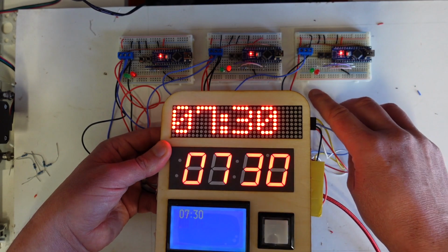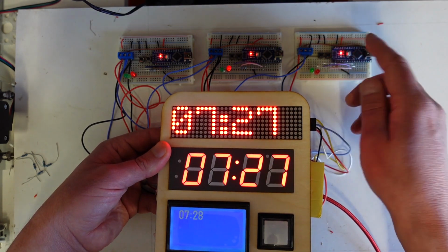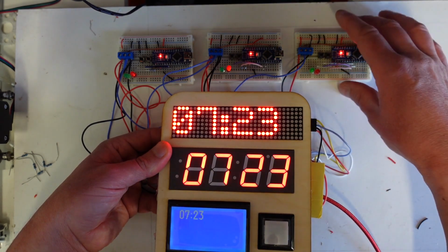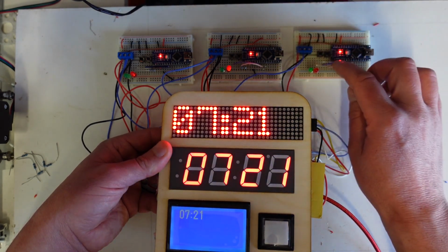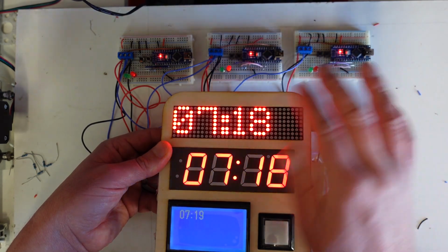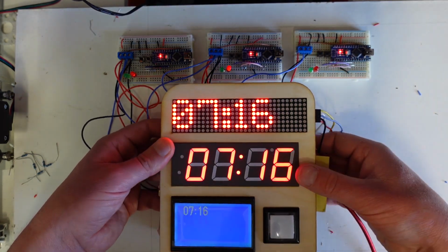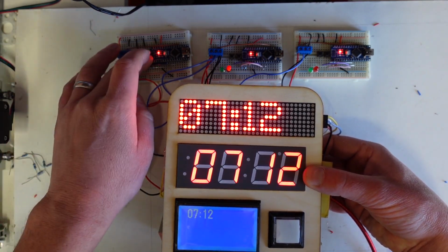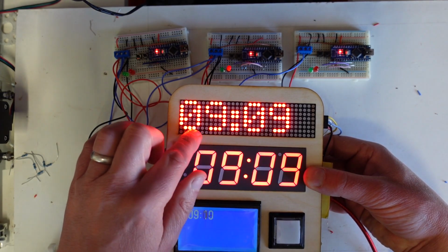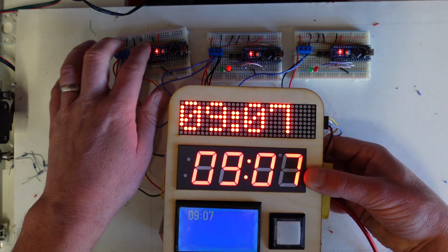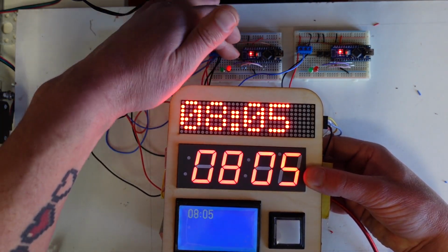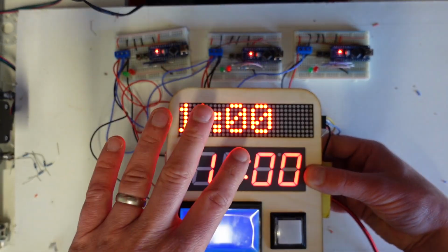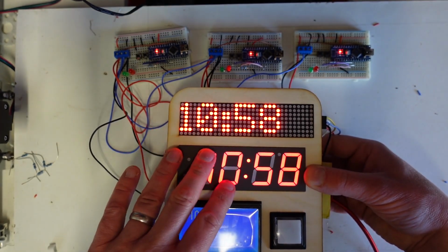So that was a solve command on this puzzle. I've got a double tap, unfortunately, which has changed the LED to green. You can just about see that's a bit faint. Probably need to reduce that resistor value rather than red, and it's increased the time on the clock. And if I do that on one of the other ones again, oh, that was a strike, so I got that wrong. In fact, you can see something's a bit weird. I'm getting double button presses on the buttons here, so I just need to check that I'm actually sending the right signals. But I am at least getting communication from the devices to the controller.